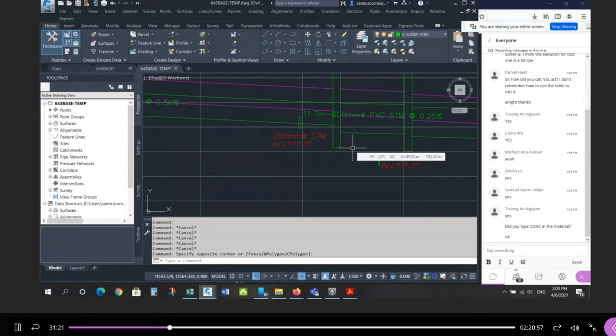So one thing I did to fix that problem that I uncovered, these backyards from the south limit of the site not being high enough, is to flatten the sewer. Okay, and I made use of that absolute minimum 0.25. Now I'm stretching it a little bit. If we go back to the standard,